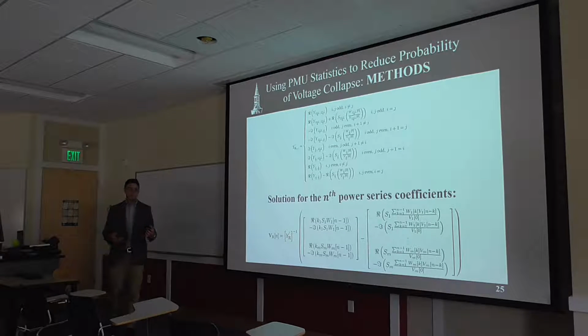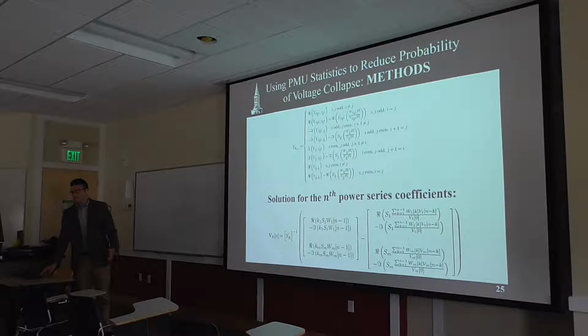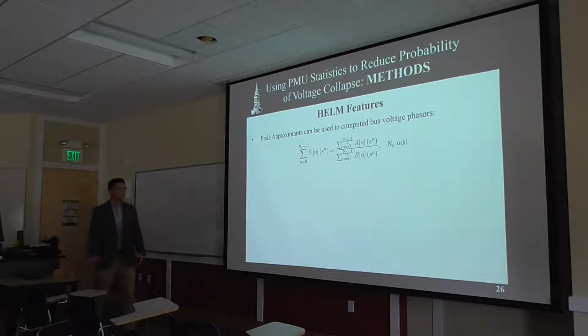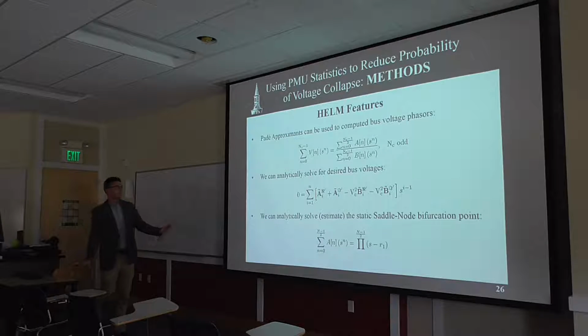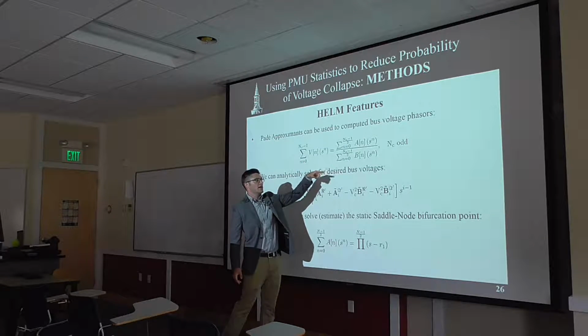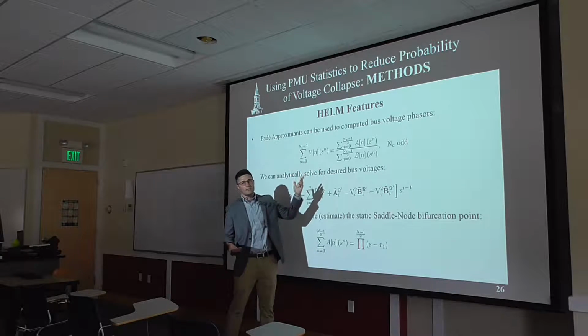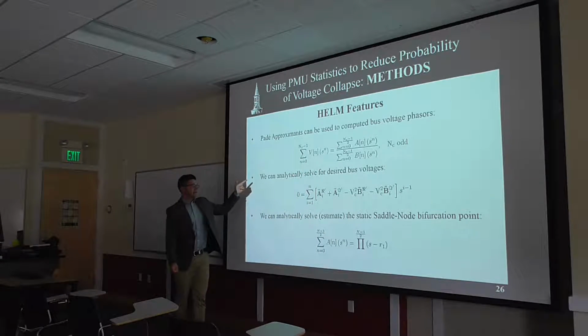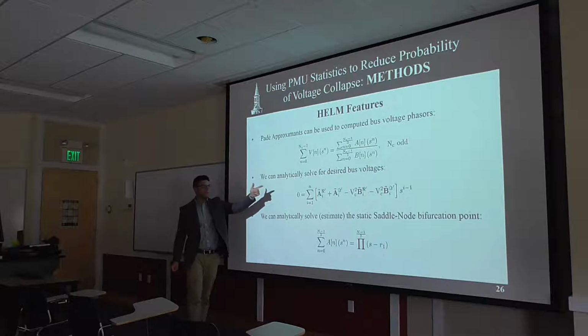We need to achieve sufficient accuracy for our CPF solution. So HELM is really cool, has a lot of really cool features. First off, once we have developed the holomorphic functions, we use the Padé approximation to evaluate it for any given value of S. Second, we can analytically solve for a desired bus voltage.